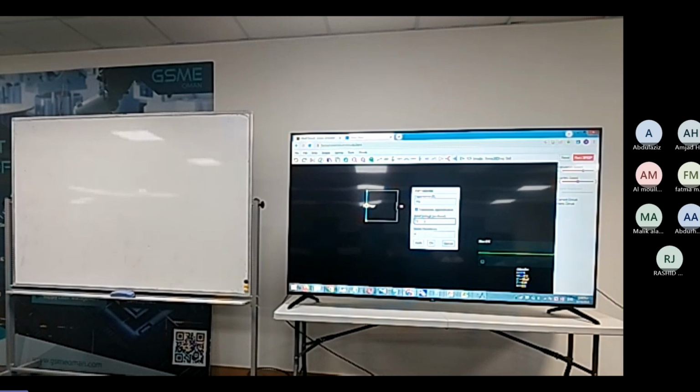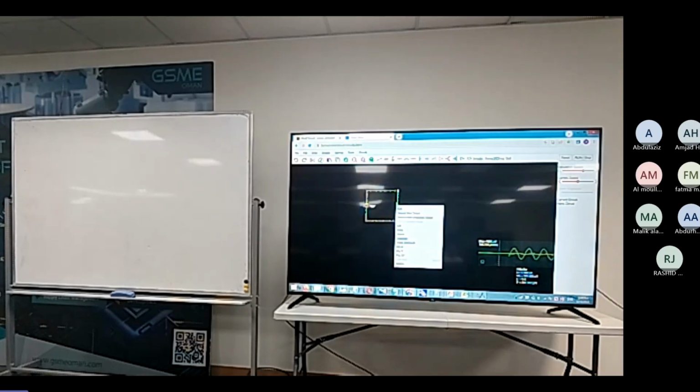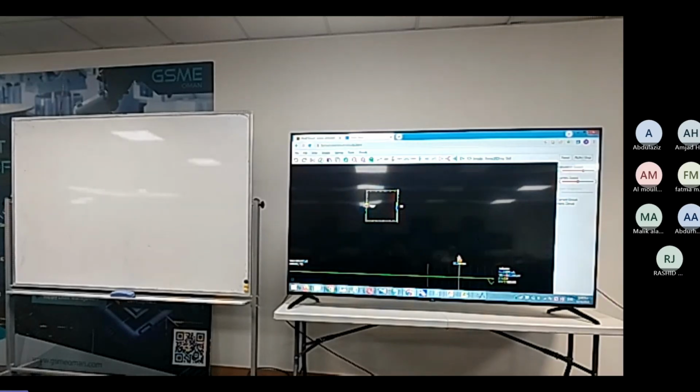The energy basically keeps moving between the capacitor and the inductor. And of course, if you have a resistor, every time it moves back and forth, some of the energy is transferred to the resistor as the current goes through it. Every round that the energy comes out, the magnitude of the voltage and current comes down. That is the damping, that alpha.